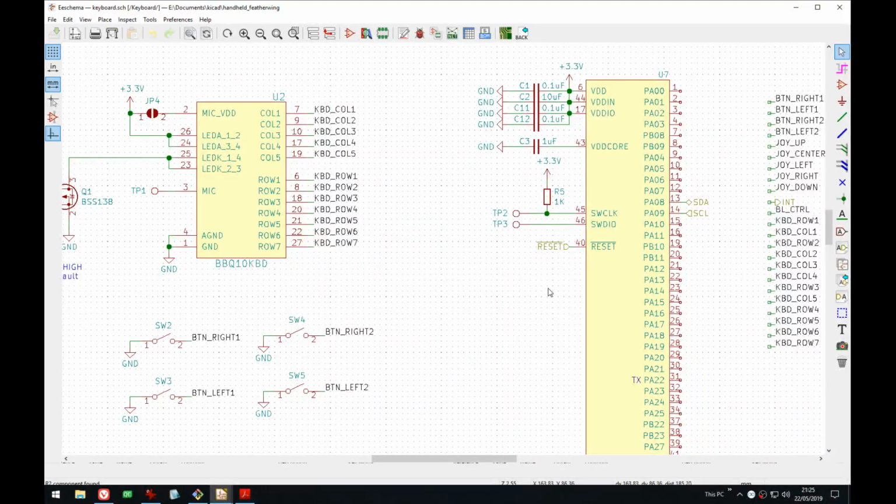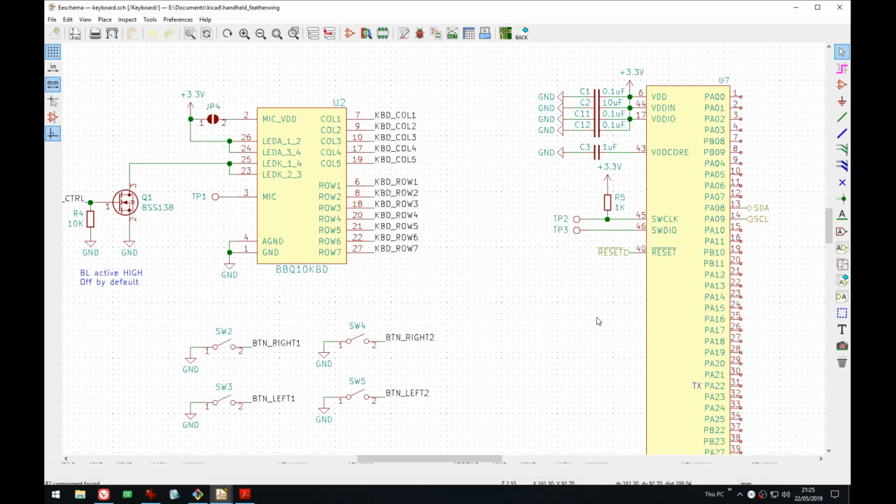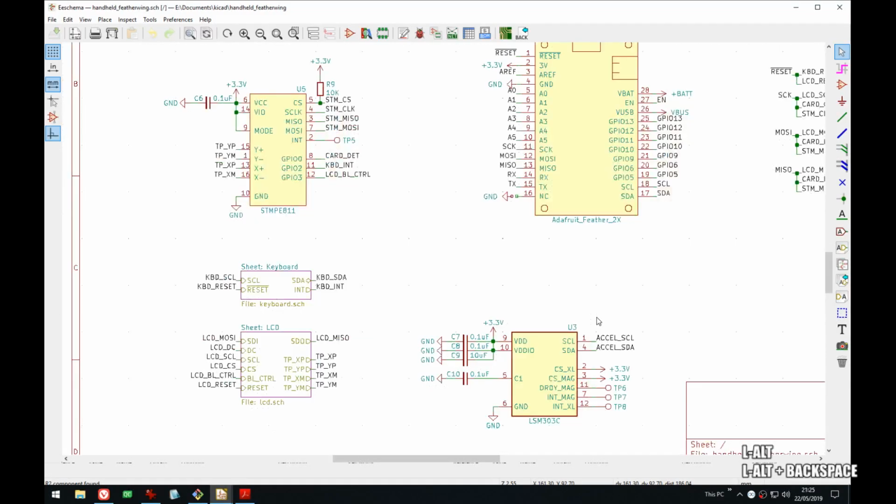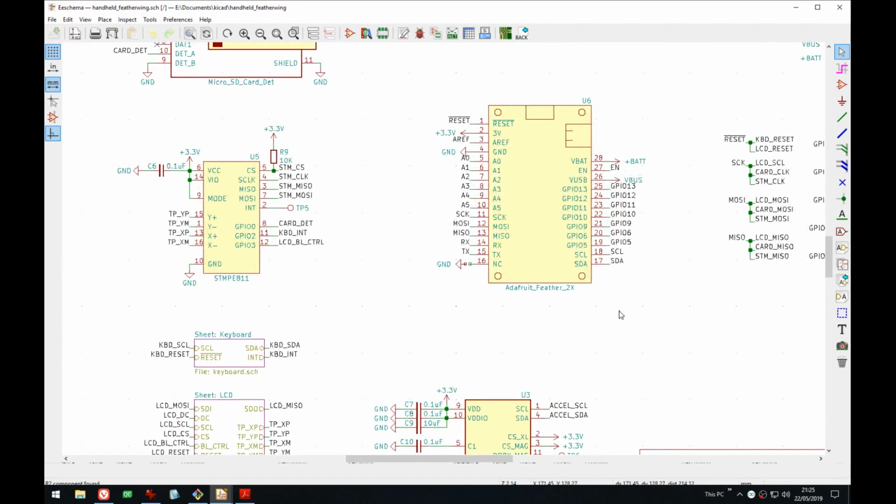I'm not saying it's easy. It comes with experience. After some time, I think you build up a library of your favorite parts, and that's just your go-to, even if it's not exactly within spec, like an LDO provides more current than you really need, but you have 100 of them in your workshop, so you just go for that one.